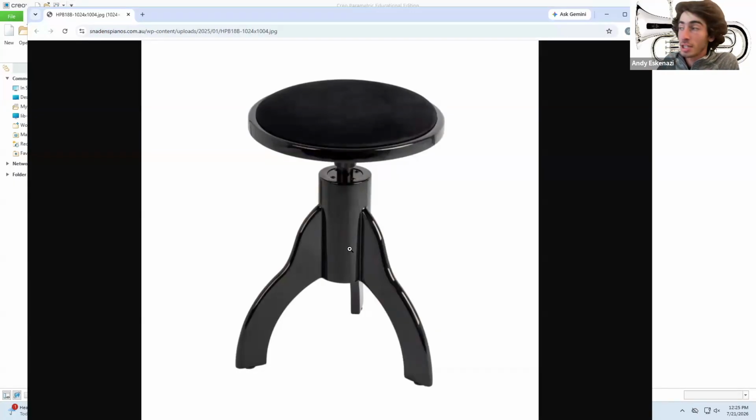We can start, for instance, by doing, well, my approach, even though there won't be a ton of approaches, would be to draw a cylinder, very easy, and then we can draw one of these little legs. Then we can do a quick circular pattern by 3, since it has 3 little legs. And then we can draw a little extension from here, from which we will have the actual seat. Something very simple, not too difficult. And then we can add a few fillets and take it from there. So let's design that.